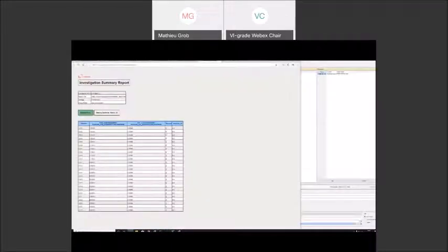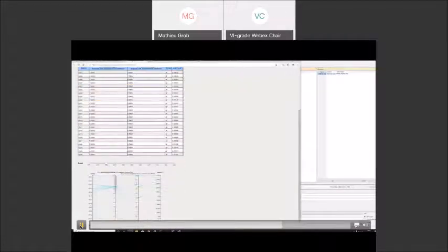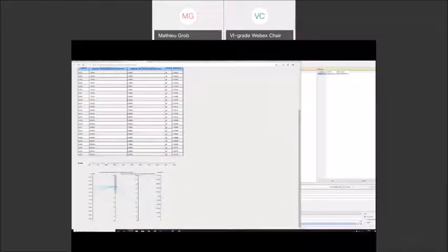And so what you can do is investigation mode. That is, you define a batch of parameters you want to explore. For example, you want to explore many different suspension settings between different types of setups. And so you can run thousands of simulations in one batch. And then at the end, visualize what is the best combination of parameters to obtain the performance you want.